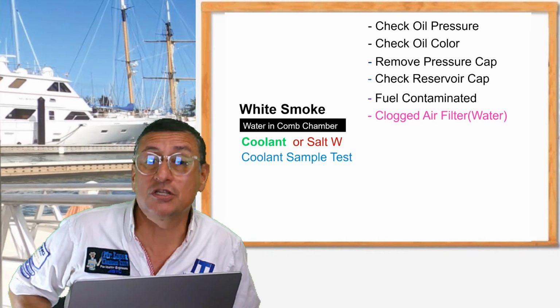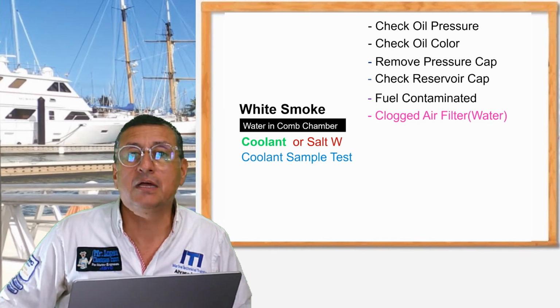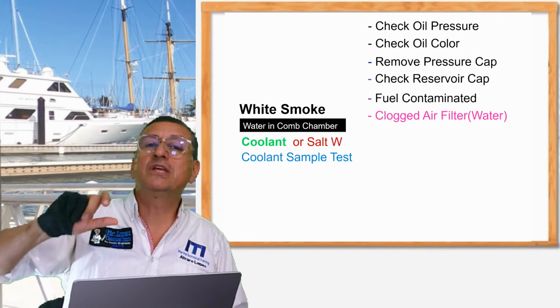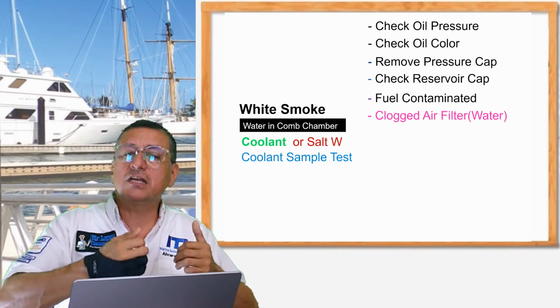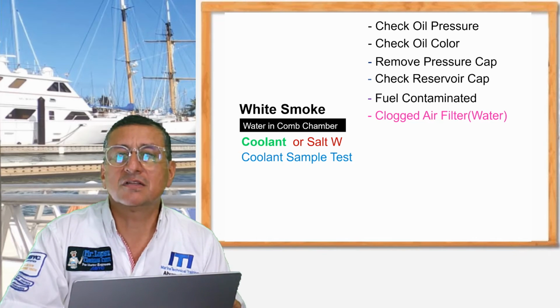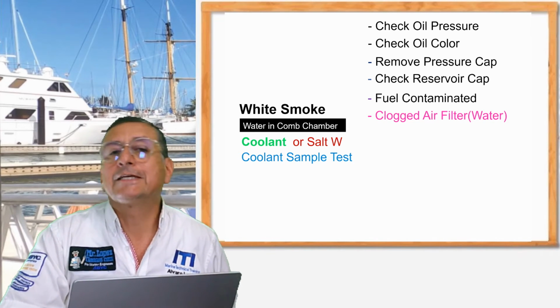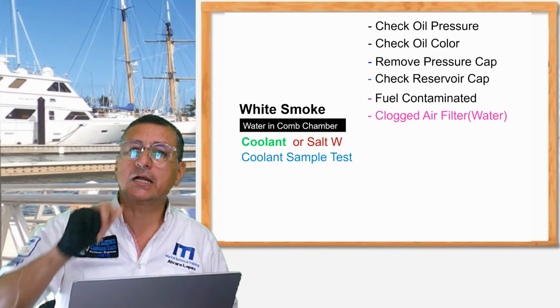Remember that the suction, the negative pressure when the piston is going down, is very high. Yes, this is possible. During the cranking, it sucks water into the combustion chamber because the valves are badly calibrated. The valve lash calibration is not good. Yes, this is one possibility during the cranking.